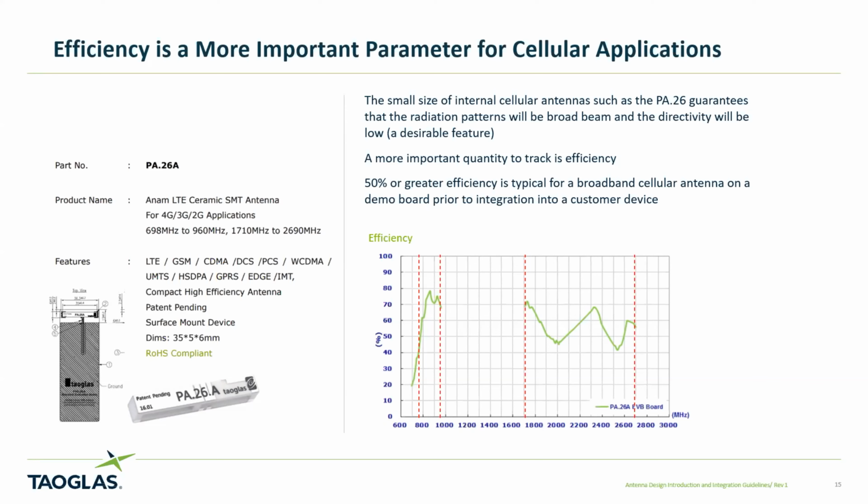Yeah, go ahead. So I know there's actually a couple more questions, and I had one. I see that you're getting more electrical length with ceramics on the radiating element, but on the ground plane, it seems like we're stuck with a huge size. Are there dielectric loading methods or something like that that could address the ground plane side of the problem?